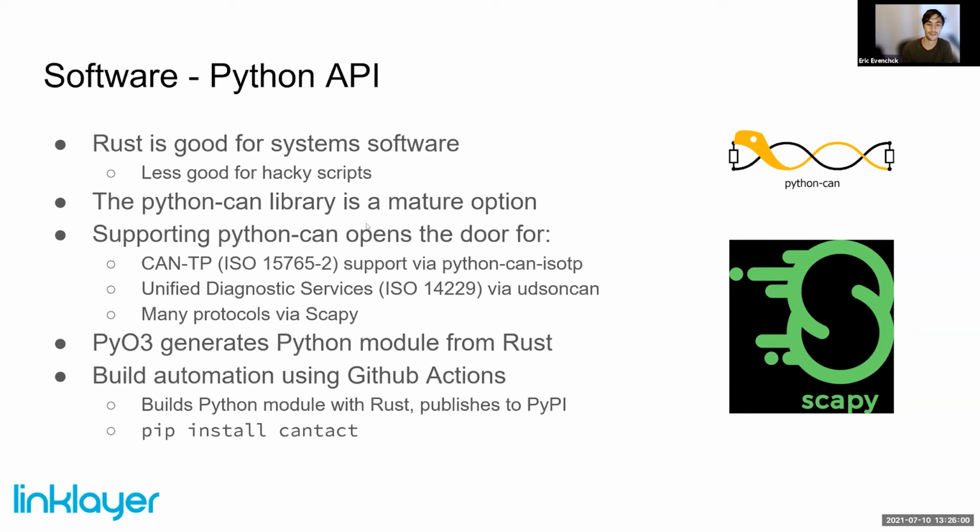And then there's a lot of other stuff that's supported through Scapy. If you haven't played with Scapy before, it's a great language for dealing with packet encoding and decoding. They have their own DSL that makes that easy, but it also now has a ton of support for automotive-specific items. And that is extremely useful if you're trying to build out either faking being a scan tool or even faking being an ECU and talking to a scan tool. It gives you a lot of tooling that makes that way easier than doing it by hand.